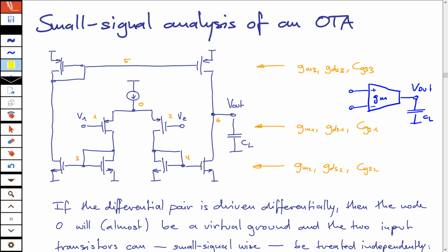I made an error in the common mode, this I will tell you later. But here I would just like to reiterate how to analyze it in the differential mode. So if you have already decided that you want to look at differential input, then you can simply say that you have here differential voltage. So half of the differential voltage is at this node, and half of the differential voltage is at this node. So the difference between V1 and V2 is actually Vd.